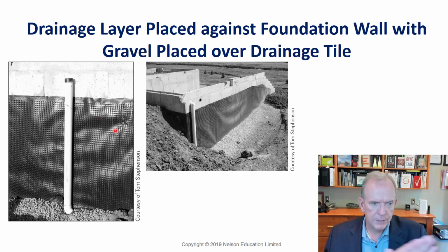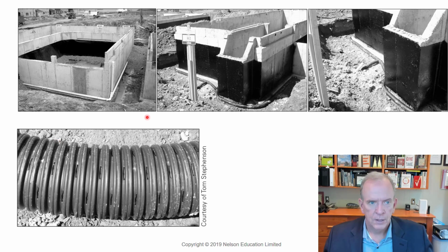And if any moisture happens to get through the drainage layer, through some of the joints and seams, it'll quickly fall straight down below ground, to the base of the foundation, down to the weeping tile, and then it'll be taken away. All right. And these are for the rainwater leaders. So this is your system here as an example, and your weeping tile is a different system.